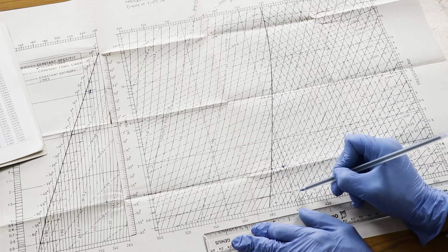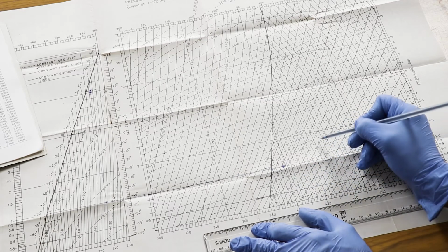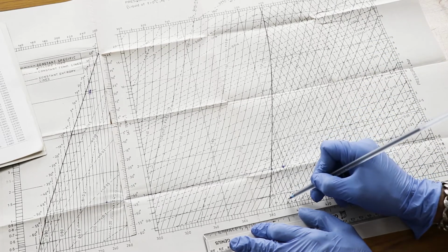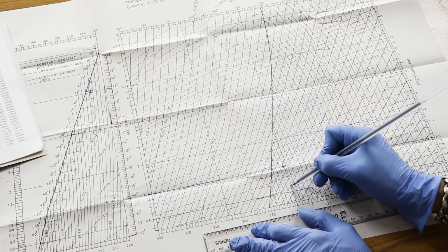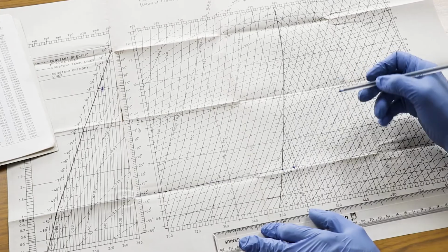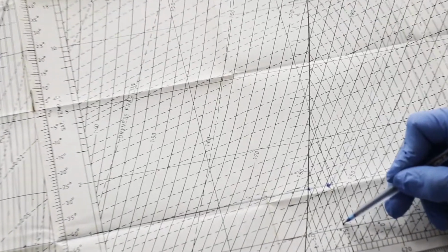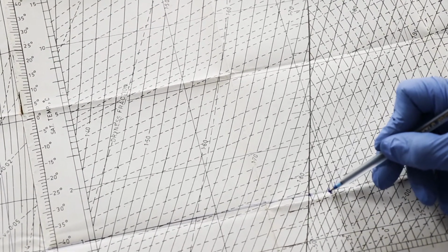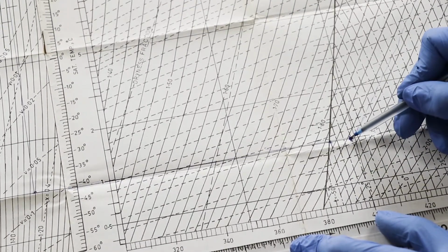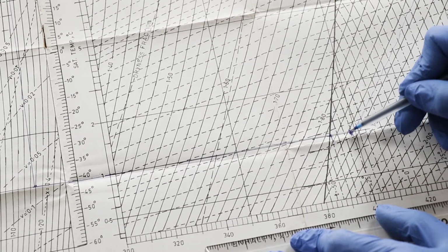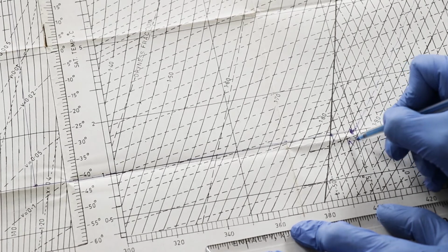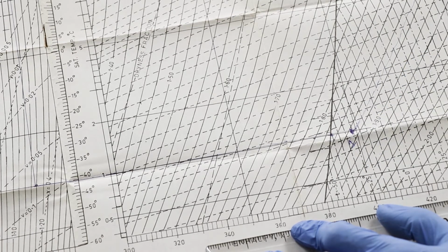These are the constant entropy lines here. So you can consider this as the 25 degree line, and the intersection of this pressure line and the 25 degree centigrade, maybe 26 degree, 1 degree more, is the first point. We call this point number 1. At this point, the refrigerant enters the compressor.